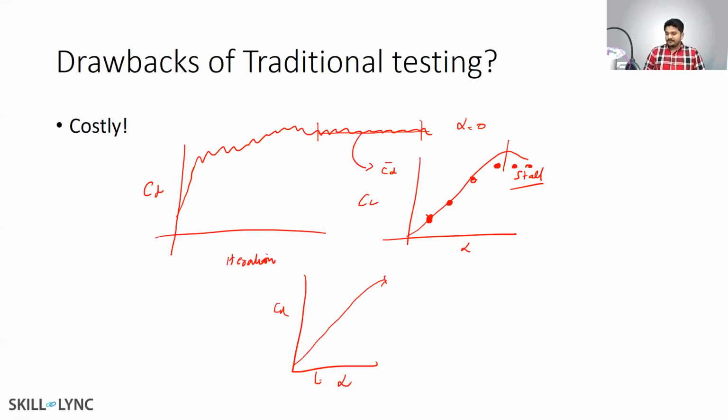Shivananda, what should be the range of error? That depends on the quantity. Usually for drag coefficients, if you're using the right turbulence model and computational mesh, you should be able to get within 5%, especially in the no stall area. This is the stall region when the flow separates. Before the flow separation, your error should definitely be less than 5%. If it is not, then most likely you're setting things up incorrectly.